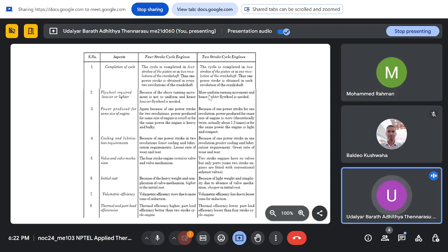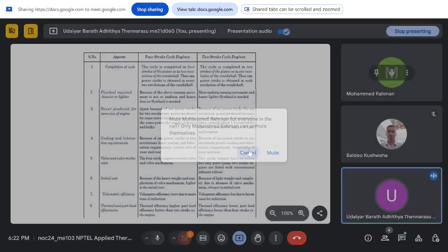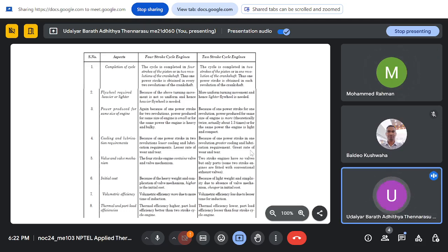Flywheel: what it basically does is, you see the cycle is continuously rotating. Your crankshaft is continuously rotating, but your power is getting generated only once out of 4 strokes, and your output requirement is a continuous requirement, right? So the power which is coming out is controlled by this flywheel, which smooths out any sudden variation. It is basically a mechanical storing device, like a battery. You are charging it in the working stroke and discharging it in the other 3 strokes, and using that power to keep the cycle running.